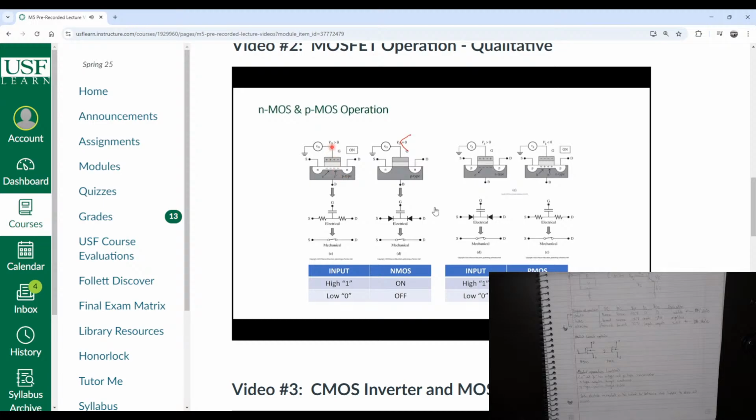So if you apply a high enough positive voltage here, and you attract a large enough number of electrons here, the region right below the oxide will have so many electrons that they will overcome the initial number of holes that make this p-type, so they will change this region to n-type. So you will have a region here that's n-type and another region here that's n-type. By applying a voltage on the gate, a positive voltage in this case, we form an n-type region, which we call a channel under the oxide. So now we are connecting this n-type region with this n-type and another n-type between.